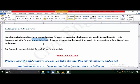This is the main benefit of this admixture that we use in concrete. Because of the minute bubbles produced in the concrete, it acts like a ball bearing, okay.